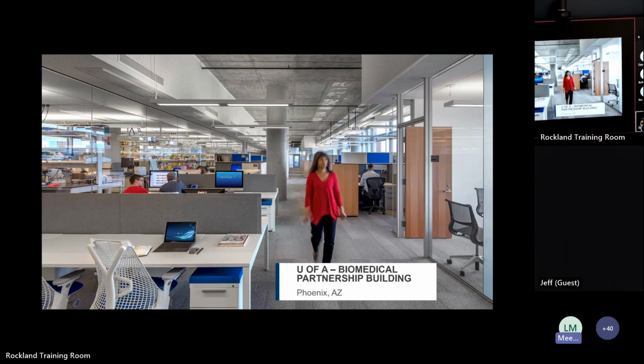Does everybody see where the other units are as well? Take a guess. In the soffit, yep. So the perforated soffit here, and that's a horizontal unit because you can see the wider face with access fasteners on that side. So you don't really need to maintain much, but every once in a while, if you have hospital rooms, lint or fabric that's getting up there, you could just vacuum that off, clean that off pretty easily because it's not a wet coil again.